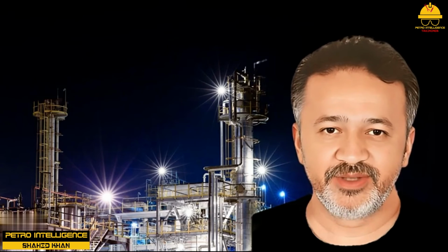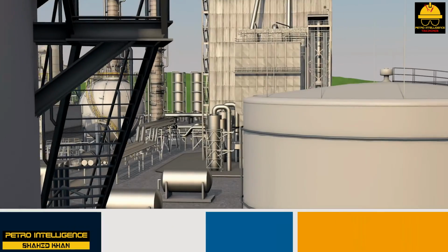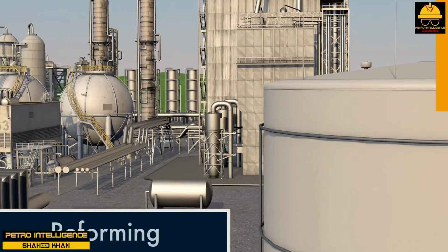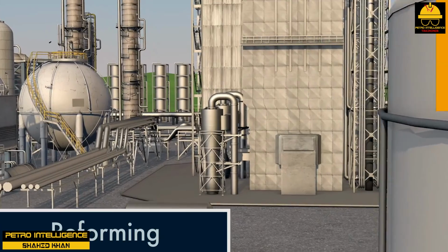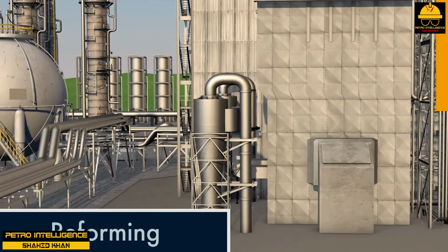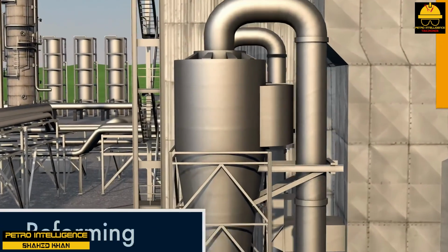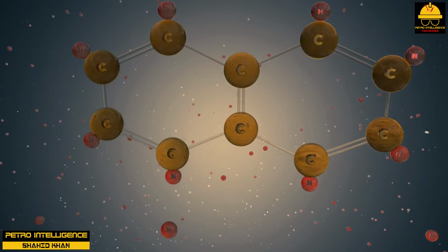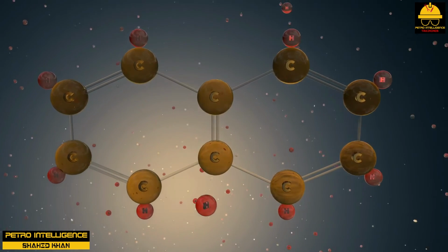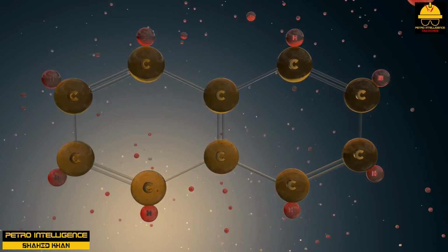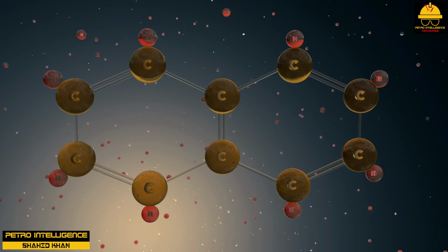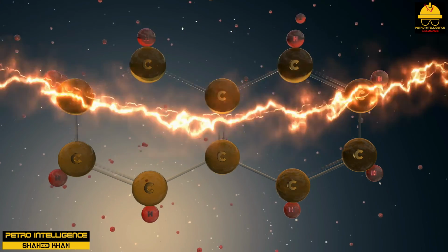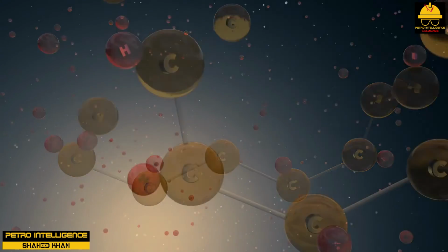Reformer, fixed bed, reactor. Reformers are designed to change low-octane naphtha into high-octane reformate. The gasoline your car runs off is composed primarily of naphtha. In this process, naphtha is heated up in a large commercial furnace to a specific temperature that brings the liquid to its boiling range. This heated vapor enters the top of a large, fixed-bed reactor filled with catalyst.